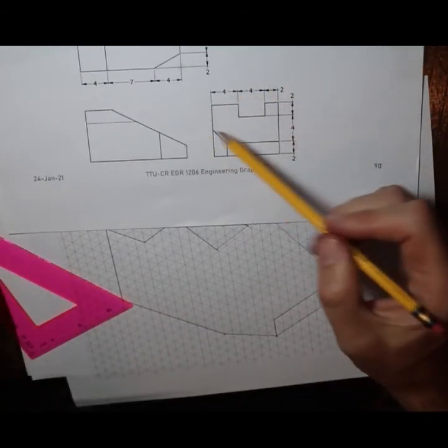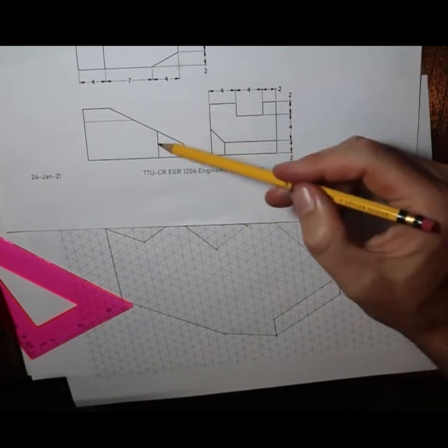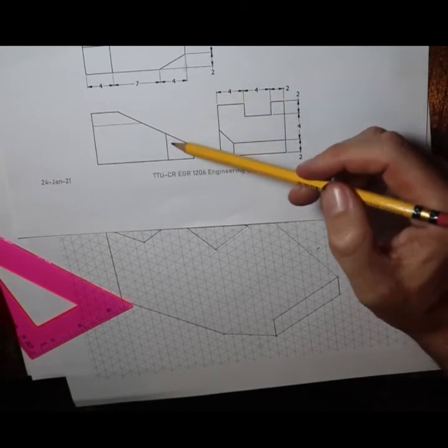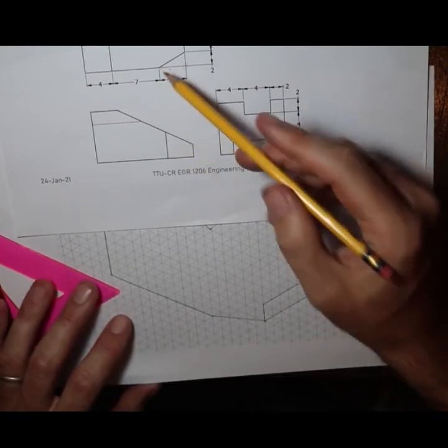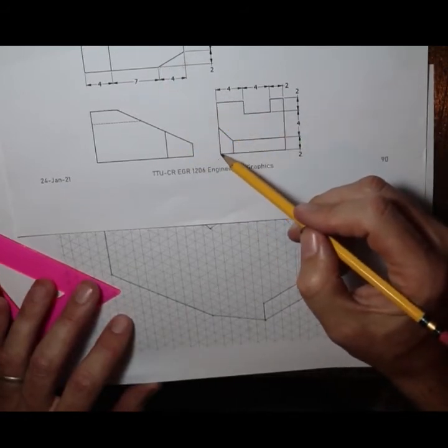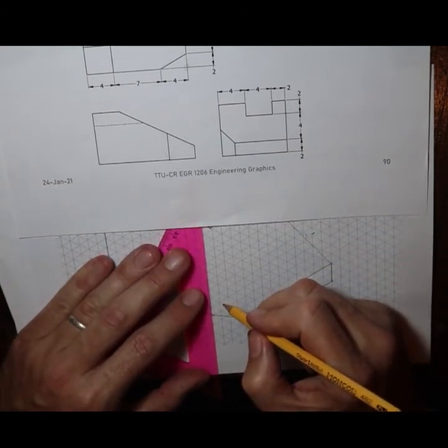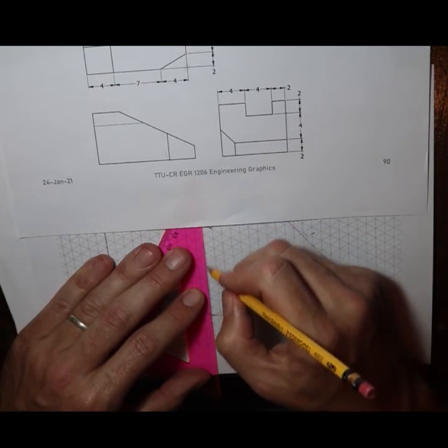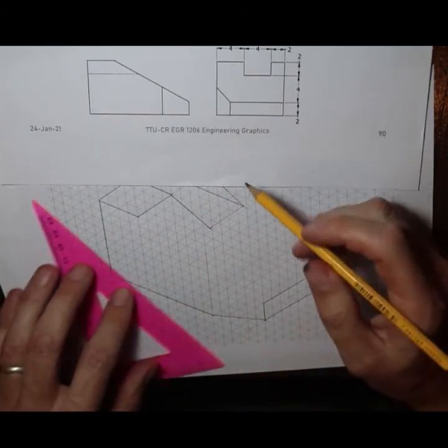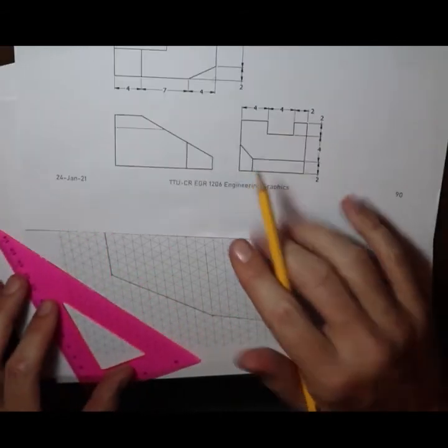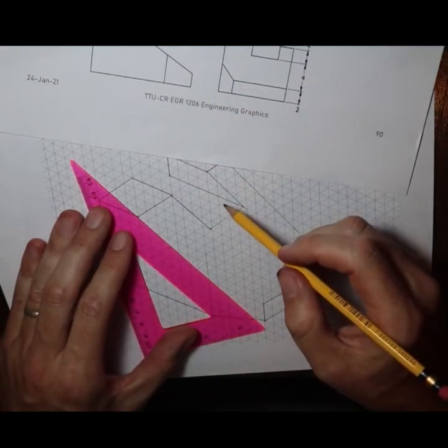And now we come to our problem section. The most difficult part here is this area right here. So what do we do? Well, we know where this line is, we just don't know how long it is. We know that it goes straight up, and we know that it starts right here, right there, and right there. So that's what we'll do. We'll do another construction line that is here and goes straight up. That very thin line here. And now we also know that this line here coming down is of course parallel to all the other ones that are coming down.